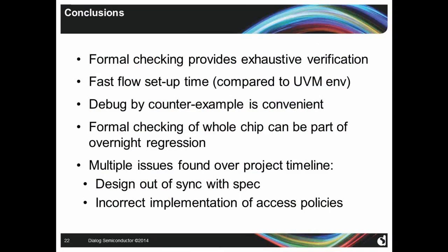So our experience of this particular flow, it was pretty easy to set up compared to our previous experiences with UVM, and trying to achieve our register coverage. The counterexample debug is very convenient, quick, and we could execute it as part of the overnight regression. And we did find some issues.